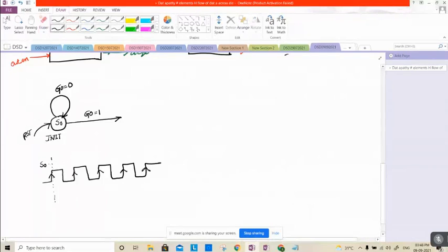Right. So if this is an initial state, suppose I am giving the go value equal to 1 here itself, will it enter into the next state, or stay there? The clock must come. Right, before the clock itself, if I am making the value of go 1, see, before the first clock is applied, initially go is equal to 0, and hence S0 has moved to S0 itself.